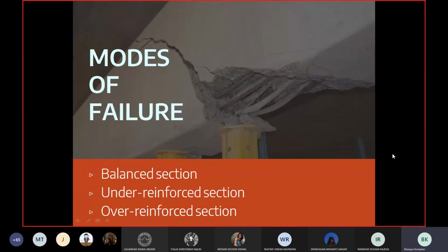The beams that we are talking about until now are singly reinforced, meaning that they are reinforced only on one side, particularly the side where there's tension. The answer to this question pertained to doubly reinforced beams, wherein the reinforcement is provided not only on the tension side, but also on the compression side. So yes, we do take advantage of steel as and when required in compression.